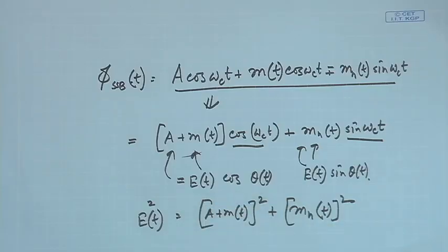It has a term which is equivalent to this mathematically, and of course, there will be a phase associated with it, theta(t), but I am not bothered about theta(t) right now, because what we are trying to do, because we have added the carrier, we want to actually do envelope detection. Okay. So, carrier detection we have already seen in amplitude modulation, we could add carrier in such a way that, with some condition, the carrier strength should be at least bigger than the lowest amplitude, modulus of that.